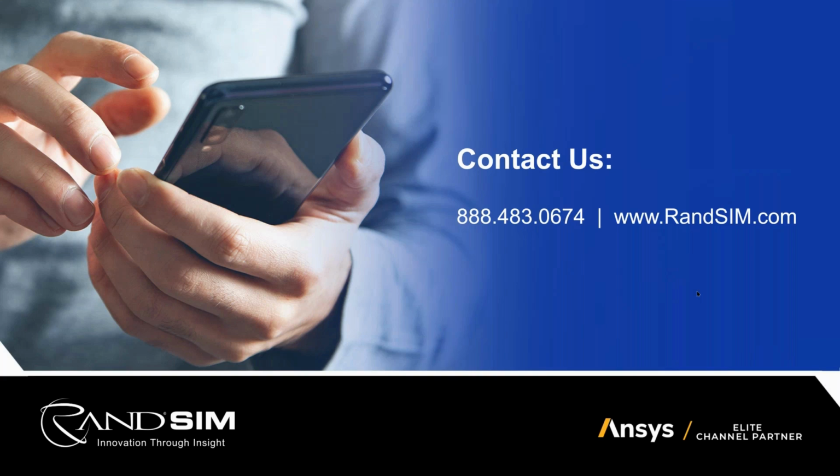Next one I have here, let's see, it's from Ben. I'm using LS Dyna now. Most of my experience is within implicit FEA like Ansys and Abaqus. Explicit simulations show stress waves propagating quickly through the solid. How do you ensure you get mesh convergence in the explicit solve? Convergence doesn't apply to explicit methods, right?